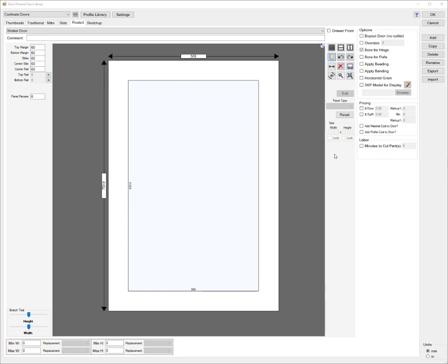In this quick video, I'm going to showcase just how easy it is to create different MDF door designs in Mozaik software. Let's get started by clicking to add a new door. Let's call this one Example Door. On the top left of the screen here, I can enter the side profile size. So let's create this as 50mm borders.